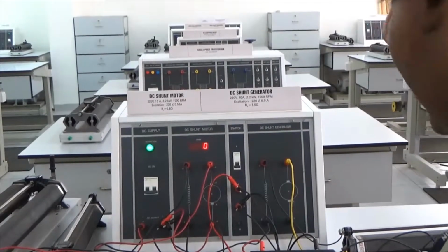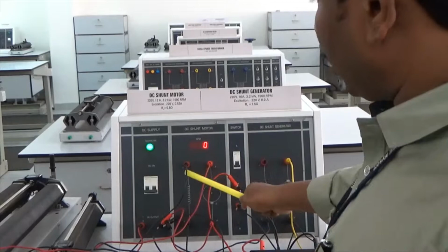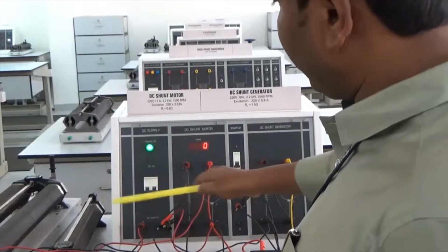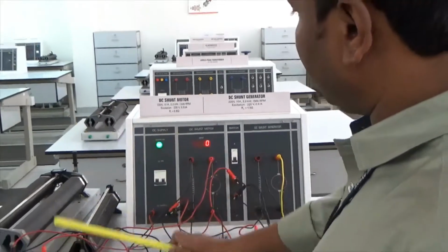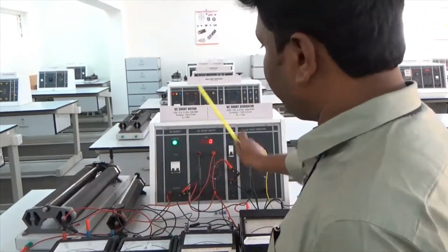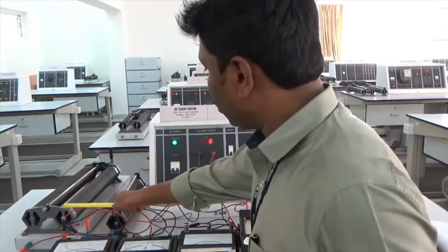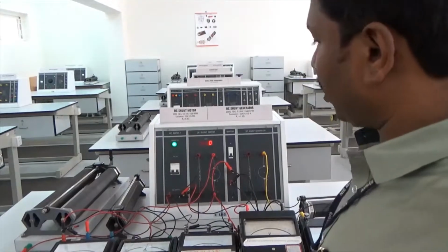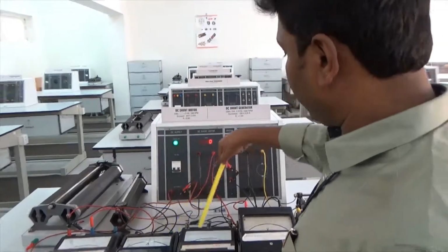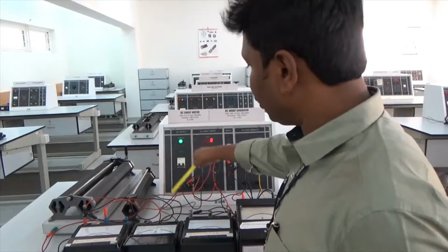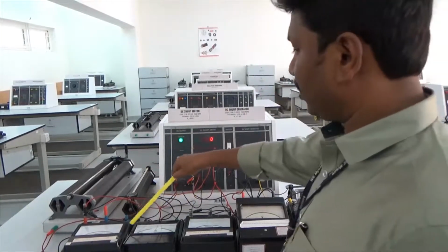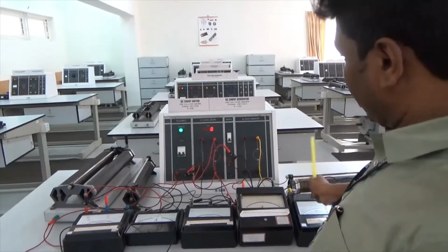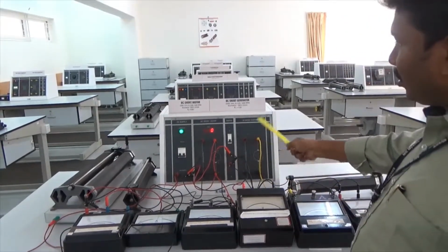As per the circuit diagram, you have to connect the motor circuit. You have a motor with armature terminals and field terminals. You have the rheostat connection for the field terminals and the starting rheostat for the armature terminals. The starting rheostat should be in cut-in, and the field rheostat of the DC motor should be cut out. For the field path and armature path, you have meter connections to measure the current. Apart from the motor circuit, you have a generator circuit.